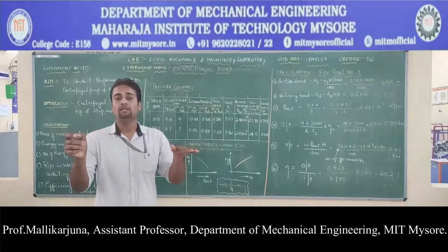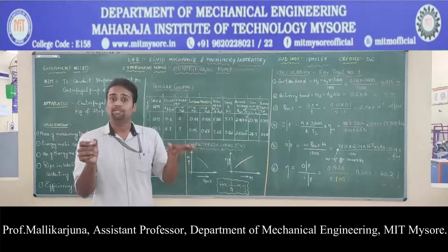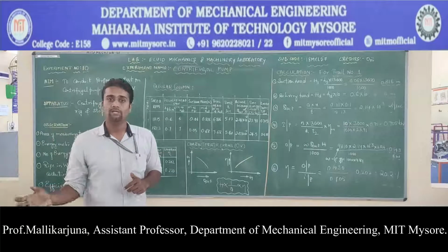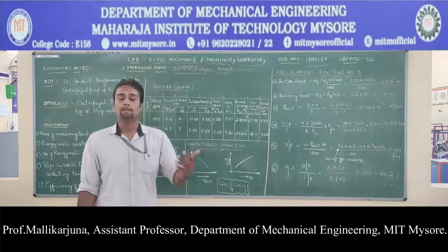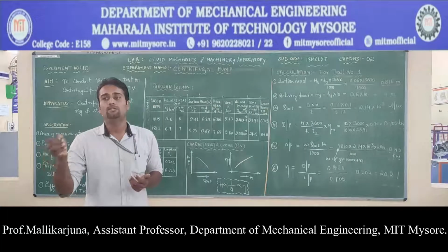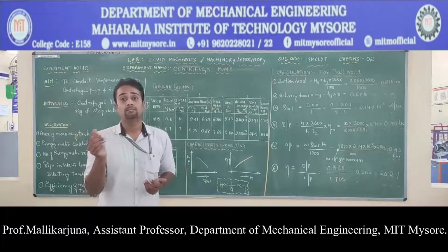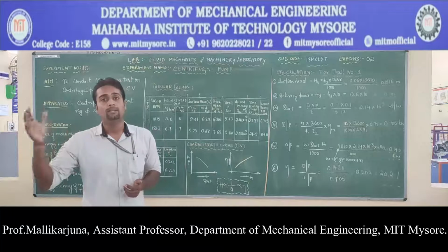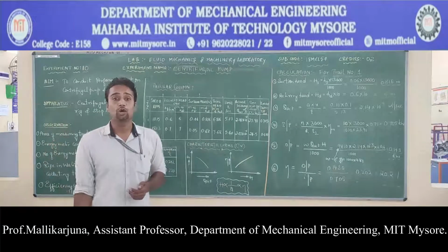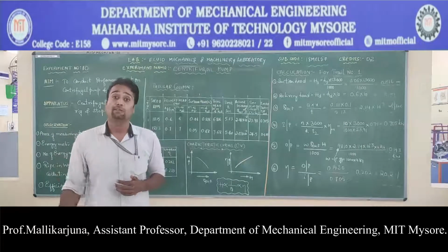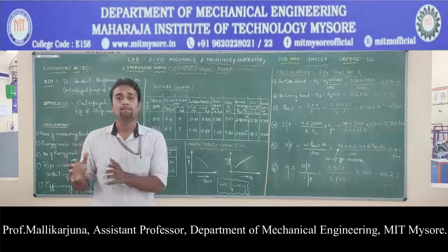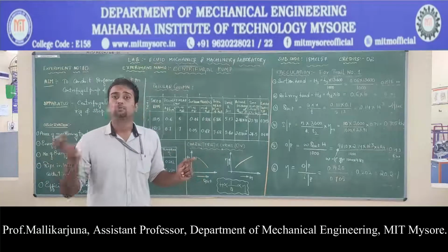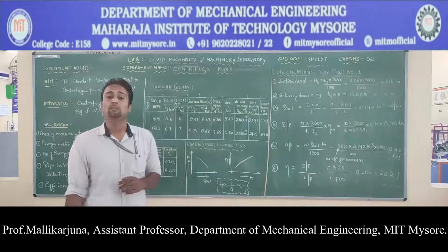This bubble formation is called cavitation because these bubbles are going to burst whenever they touch the rotary aspects or rotary devices of the pump. When these bubbles burst on the equipment, they have the effect of eroding the material. This is one of the problems. Material can be eroded. This can generate huge noise. This can set up various vibrations in the device. So these are the main problems associated with cavitation: noise, erosion of the blade or erosion of the material, as well as the vibration.